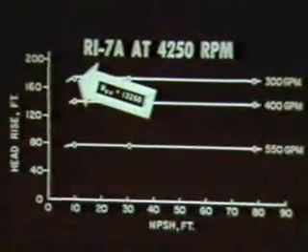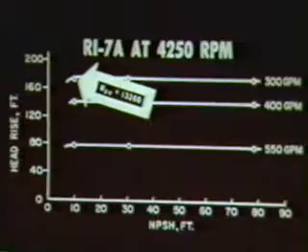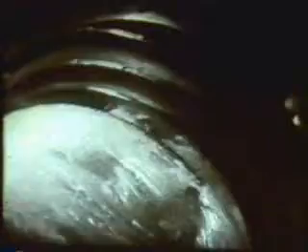Compared to the previous flow rates at this value of net positive suction head, the cavitation bubble formations are more pronounced. The cavitation pattern is highly complicated by the impeller operating further into stall.